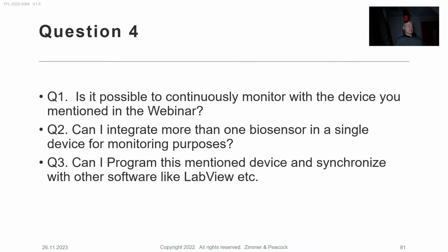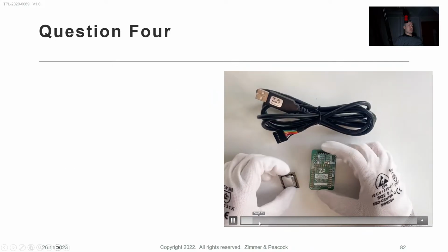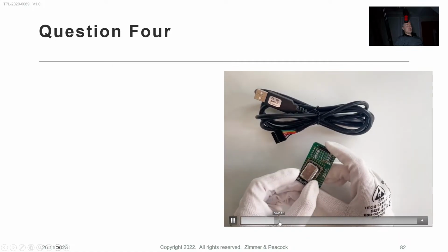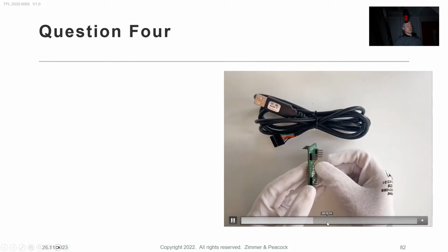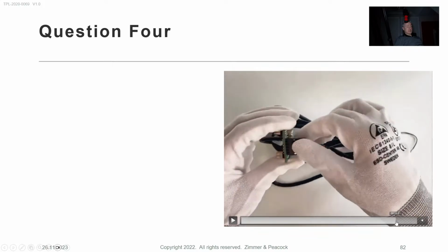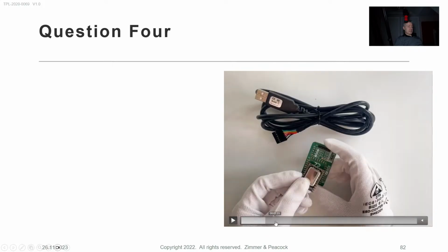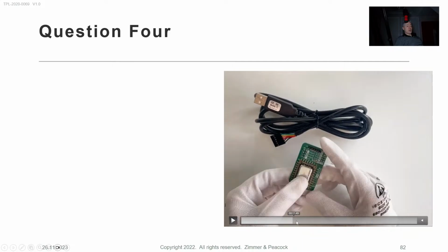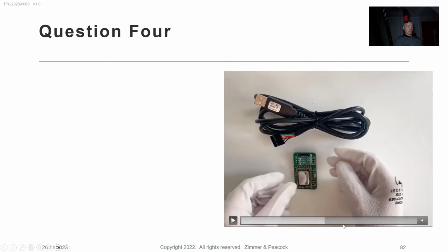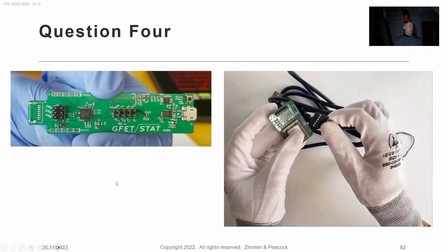The answer is yes, but I will not be able to give you direction on multiplexing it. There's one chip that they're clipping onto the board here, and you can buy that board and etc. That one chip will do one sensor. If you want to multiplex, the guy said, yeah, anyone with electronics experience should be able to sort that out, but we've had a go ourselves. We didn't put a lot of time into it, and we didn't like the crosstalk that we were getting through the multiplexer that we were making, so therefore we can't suggest a multiplexer because we haven't finished solving it ourselves.